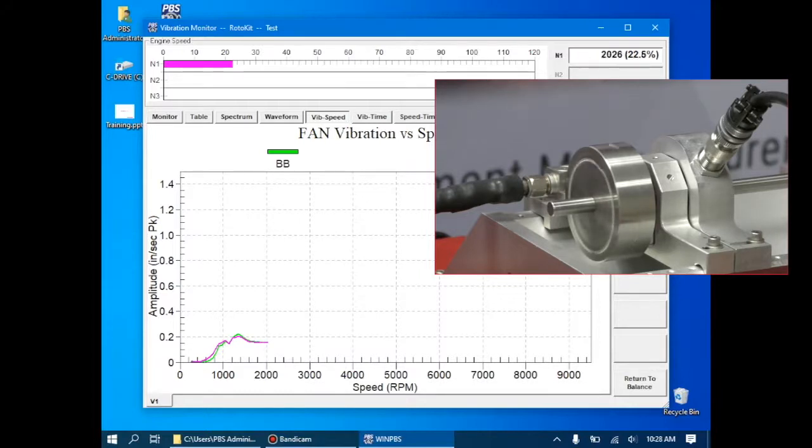When doing a trial weight run, vibrations may be larger than, equal to, or less than the original vibration. The system will look not for higher or lower, but for a difference in vibration. In this case, the vibrations are actually a little bit higher with the trial weight installed, but still well below our 1.2 self-imposed limitation. Again, we're looking for a good relationship between the broadband and the N1 curve, which we're seeing.